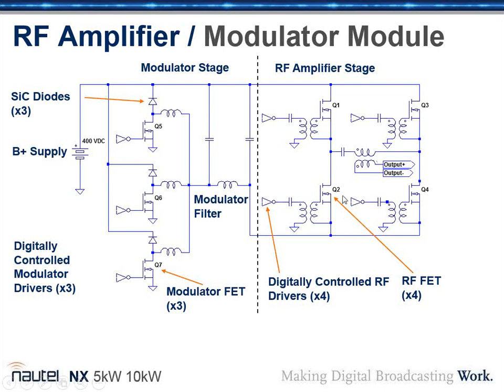Now explain the H-bridge to everybody. Okay. Again, we have some digital RF drive signals that come into the power amplifier, and those go through some gate drive transformers, just because some of the FETs are sitting at higher voltages and are not ground referenced. Those switch the FETs at the RF carrier frequency.